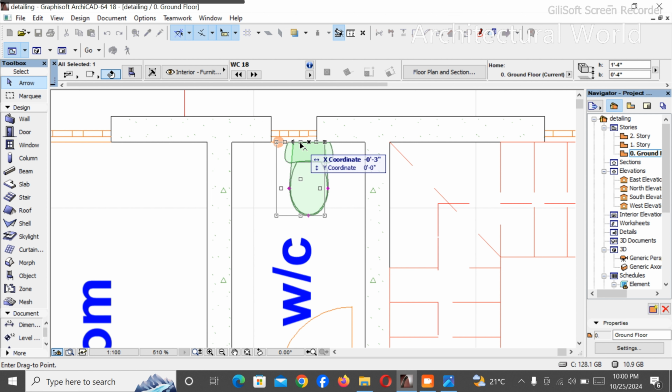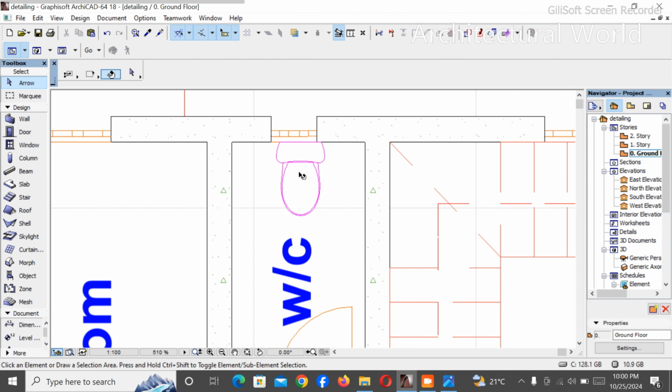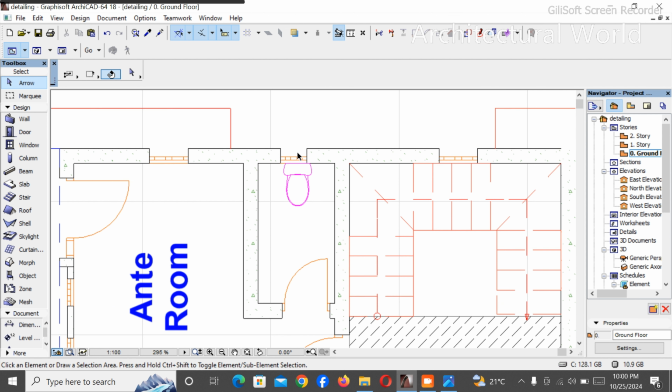That is the best place for this WC to sit at. And if the WC is sitting at the center of this toilet, it simply means you can easily connect your 4-inch pipe, your waste pipe, to flow direct to your soakaway without you experiencing any stress.